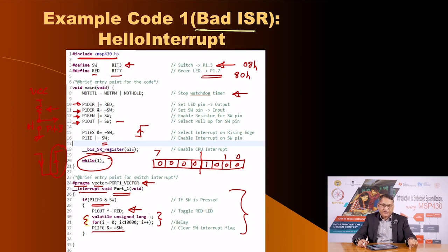In case when you press the switch, the LED toggles, and when you release also it toggles, maybe it toggles multiple times, you may think that the program is not working the way it should. And the explanation of that would be that in your kit, it so happens that the switch press and release is generating switch bounce, which we are not able to deal with, at least at the time when you press the switch.